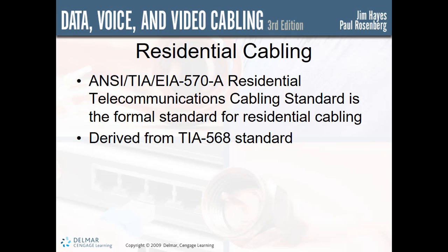And the standard specifies distribution devices for each residence. This device is a panel of sorts functioning as a type of service entrance panel for the telephone. Location, space, and electrical power requirements are provided in the 570. The distribution device must be located in a centralized, accessible location. Space allocations for the distribution device are provided based on the grade and number of outlets being served.